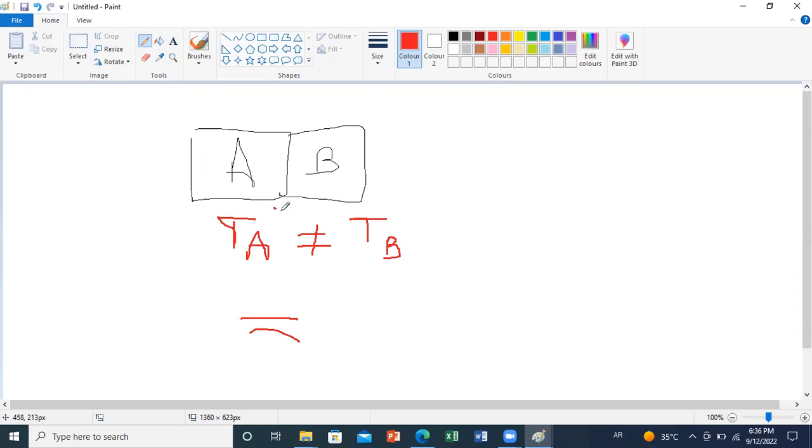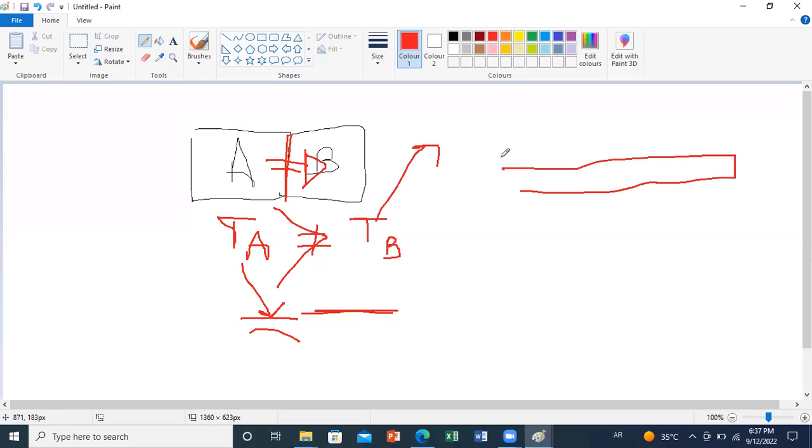So let's say TA is larger than TB. Due to contact, heat transfer will take place from the highest temperature to the lowest temperature. So with time, TA will be reduced and TB will increase until reaching equilibrium, when the 2 will be at constant temperatures. So this is thermodynamics. Thermodynamics deals with the transient processes to go from one equilibrium state to another. Now, you can have conduction in the same fluid or the same solid, so no need to have 2 different objects.